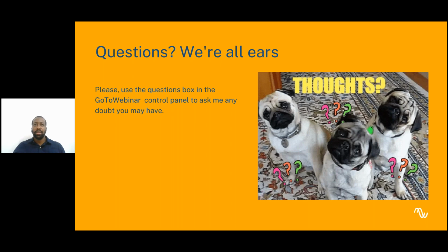Let's say, how many of those turbines are actually there. But ideally, because PV design currently for the near shading takes into account inter row, if you actually try to use that, you would need to use software that can actually run the 3D analysis, taking into account those specific turbines. Okay, so that would be my answer for it.